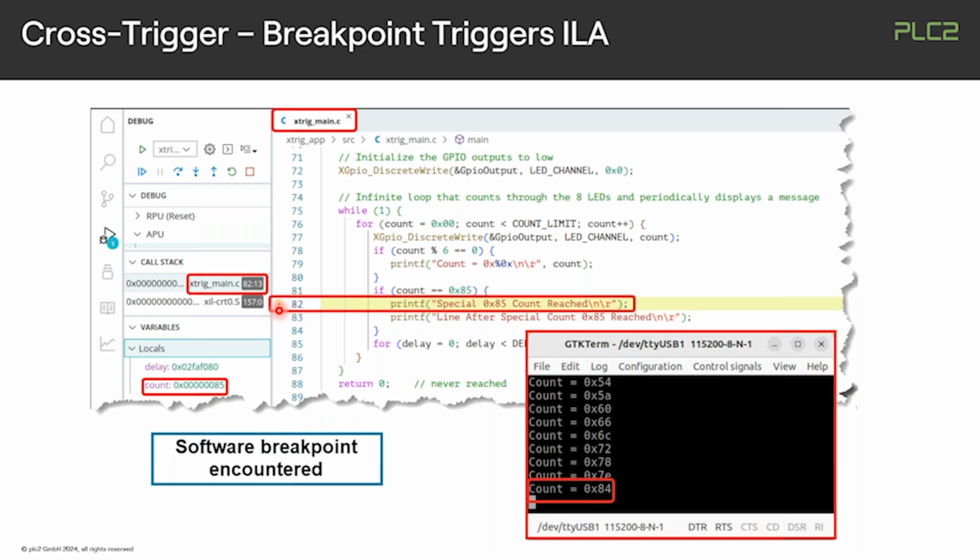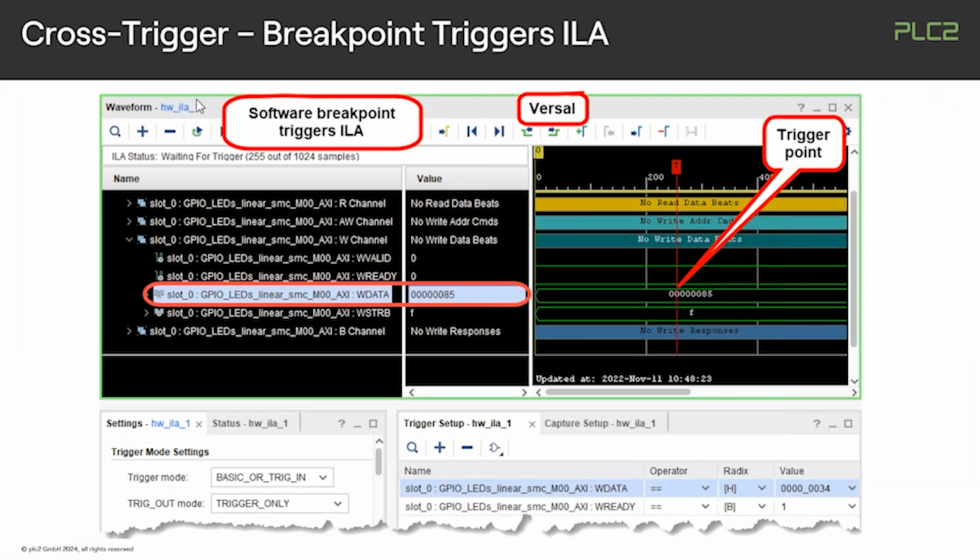And when you have now enabled the trigger, as I showed you on the slides before, and the Vivado logic analyzer session is open, this event will trigger. And therefore, you will see actually your software breakpoints as a trigger to your probe signals, which are connected to your ILA.